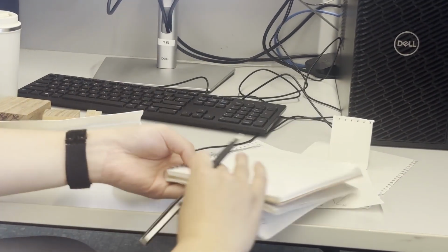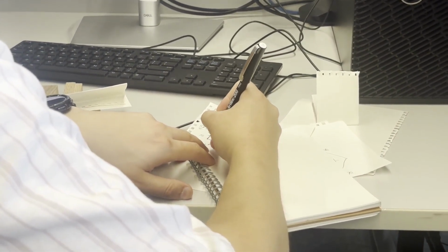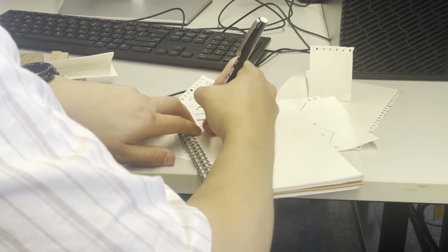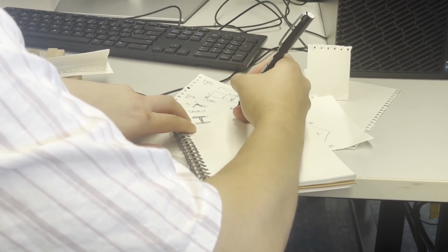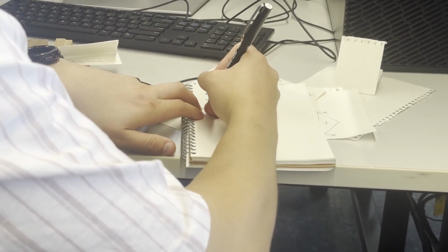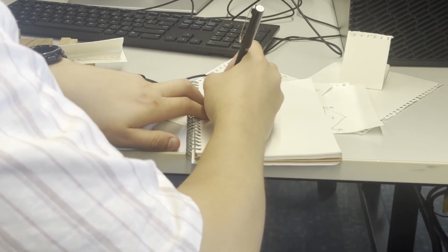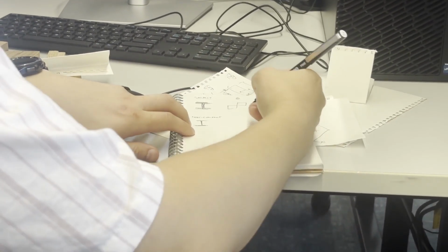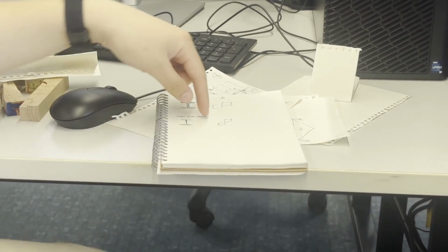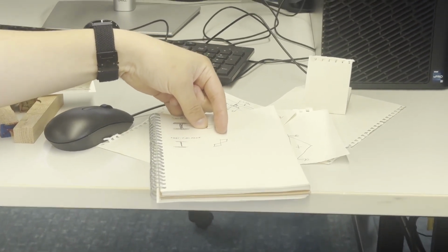Let me redraw that. So compact, to recap, would be very fat like this, and it can reach full plasticizing like that. Non-compact, let's draw it a little bit less fat. A good portion of it can reach plasticizing, but not the entire thing, like that.